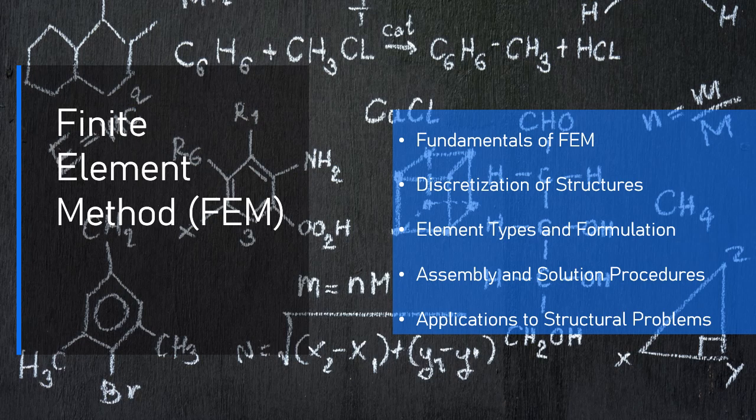4. Setting boundary conditions. Boundary conditions, such as fixed, roller, or free supports, are applied to specific nodes or edges. These conditions are crucial for ensuring that the physical system is modeled realistically. 5. Discretizing loading conditions. For each element, external loads, forces, moments, or pressures are applied. These loads can be distributed over the entire element, or applied at discrete nodes, depending on the nature of the load.